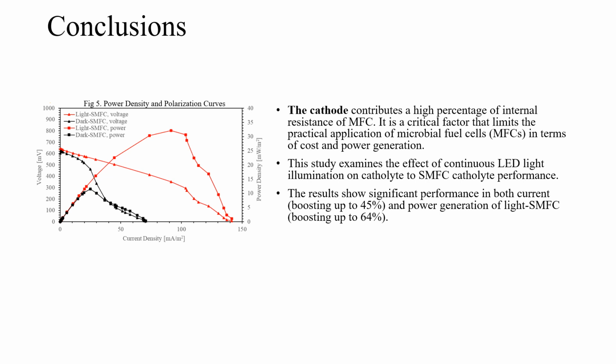And the conclusion is that the cathode contributes a high percentage of the internal resistance of MFC. It is a critical factor that limits the practical application of microbial fuel cells in terms of cost and power generation. This study examines the effect of continuous LED light illumination on catholyte performance in SMFC.